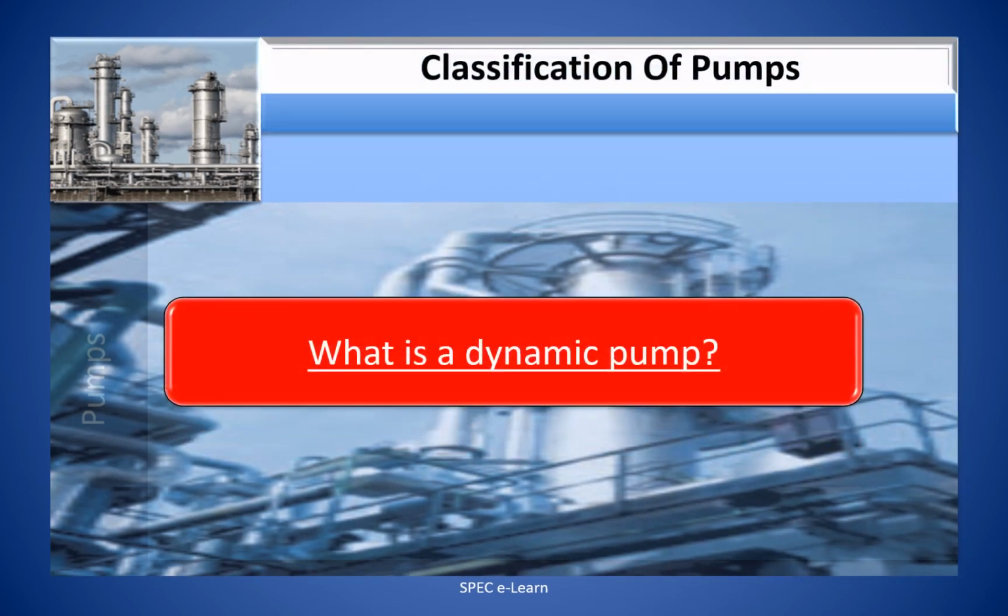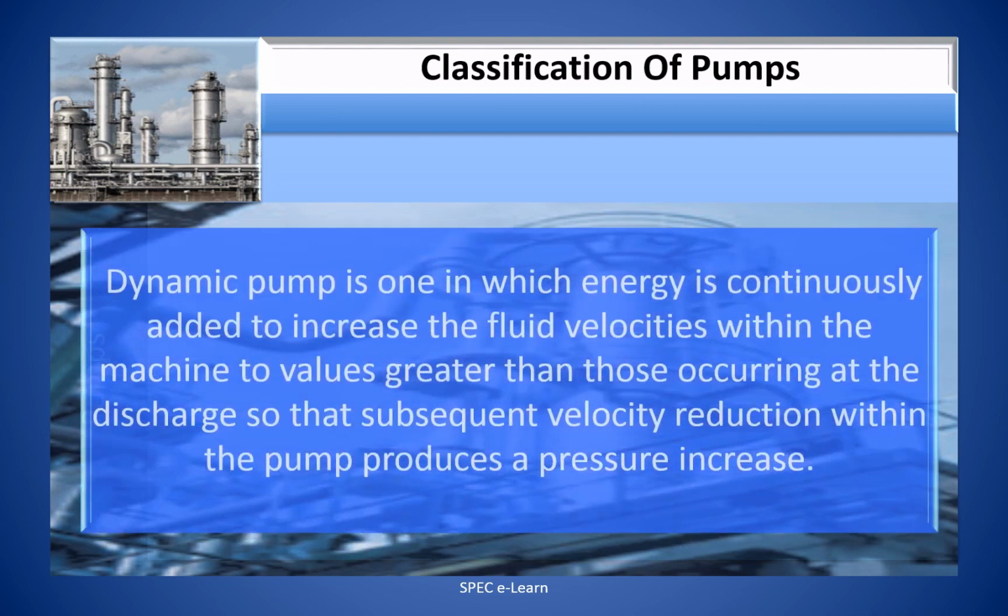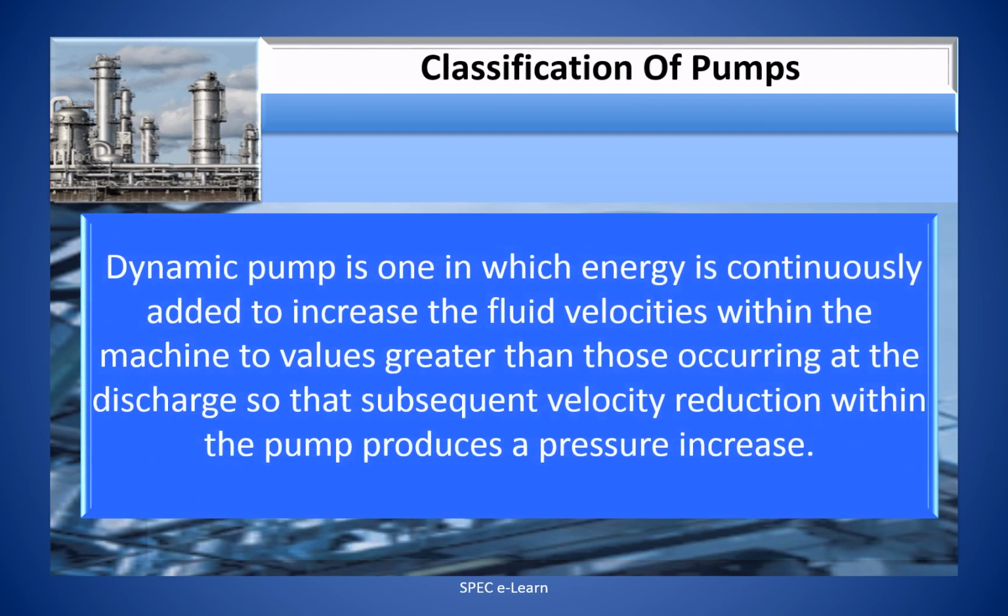So, what is a dynamic pump? A dynamic pump is one in which energy is continuously added to increase the fluid velocities within the machine to values greater than those occurring at the discharge, so that subsequent velocity reduction within the pump produces a pressure increase.